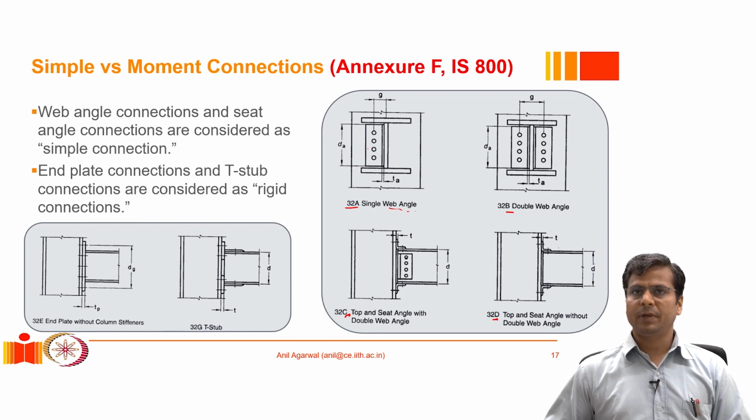That depends on the constructability and the prevailing practices. But a designer should be familiar with what parts can be welded together, what parts can be bolted, what is practical in the field, because a designer may think that I would have everything welded, but depending on the project's scope and ability of the manufacturer and ability of the construction company, they have to realize what can be done at the site, what is possible to be erected, what is not feasible to be erected, and so on. So all those considerations go into deciding where we can put a bolt, where we could not put a bolt, and where we should put a weld.